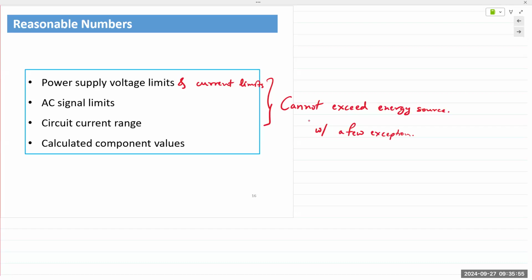And then the voltage across the output could be larger than 10 volts. The reason is that there is a capacitor in the circuit. In one half cycle, the capacitor charges. It reaches a full charge, 5 volts, 10 volts, depending on the circuit configuration. The next half cycle, it's cut off. So when the next half cycle comes along, the capacitor's stored energy is added on to your 10 volts, and then the output voltage is larger than 10 volts.